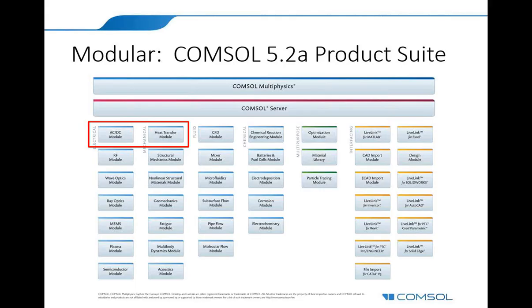Now, the first part of the example problem that I'm going to run, by and large, will be done in base COMSOL. You'll see that I have this biological tissue in it eventually. That is going to depend on the heat transfer module, but that is the only piece to it. So actually the electrical part, when we're doing DC conductive, stationary, RMS, can be done in base COMSOL. But as I start adding frequency content to my electrical problem, then we run up into the AC/DC module.